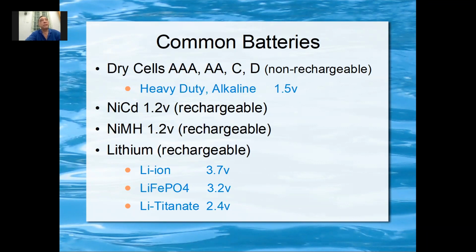I don't even want to use them, because they are 1.2 volt, and if you use 2 pieces, it's 2.4 volt, and the device expected 3 volt. When you put it in, after a while, they tell you battery low. For some devices that can operate down to 2 volt it is okay, but some just cannot.